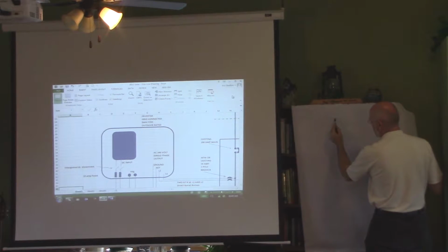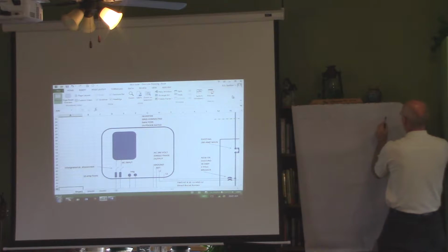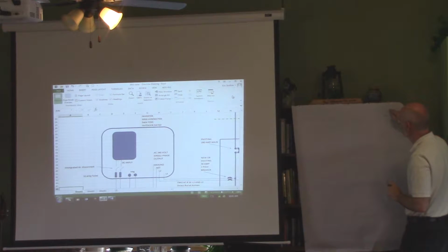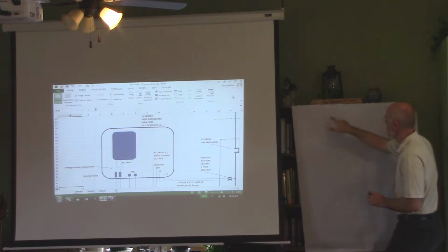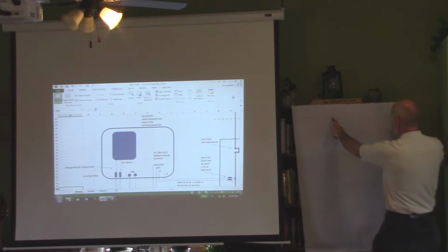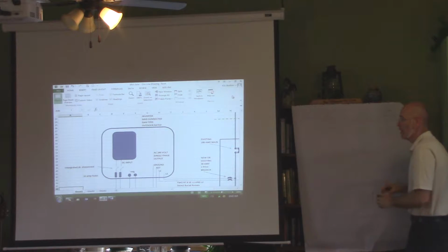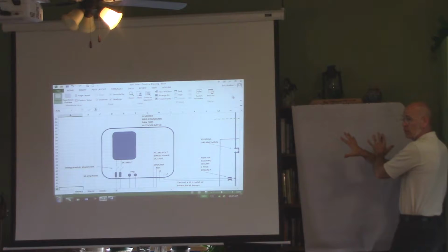These inverters, I'm trying to create that waveform. This is Eric Skelton's system over here. And over on this side is the utility. It's producing power. It goes up to over 120 volts and then down to a negative 120 volts. And it's going to do that 60 times a second at 60 hertz. It's frequency. Okay? I got to get from this to this, and I need this to match up in time exactly the same as that. So if I'm at this moment in time, I need that to be that moment in time. If I connect them out of phase, it's going to go kaboom. It's going to spark. It's going to blow up.